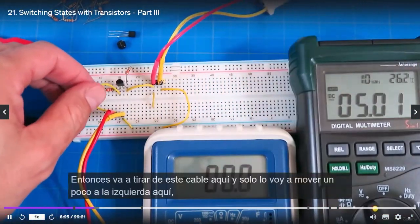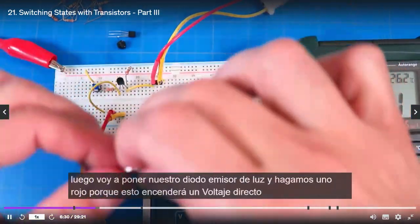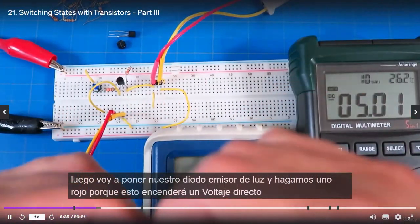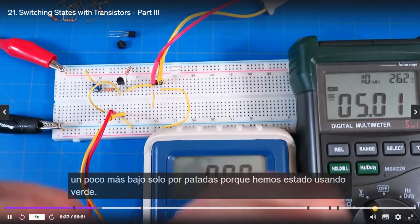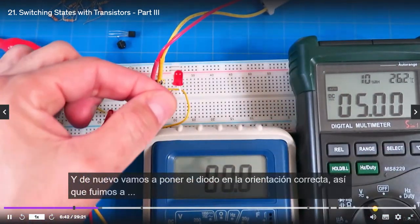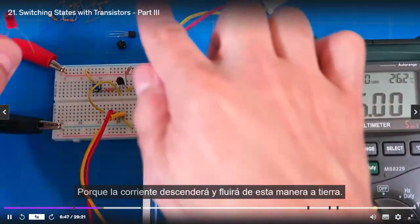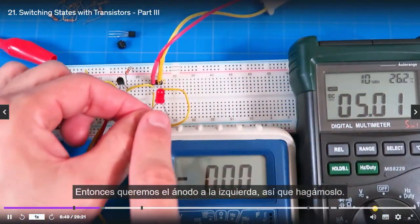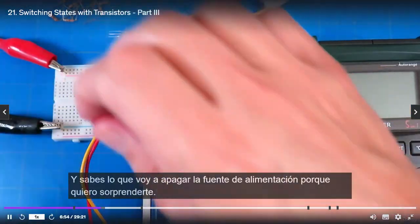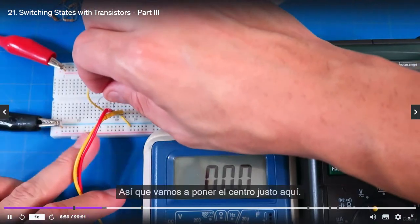So I'm just going to pull this wire here, and I'm just going to move it a little bit to the left here. Then I'm going to put in our light emitting diode. You know what? Let's do a red one, because this will turn on at a little bit lower forward voltage, just for kicks because we've been using green. And again, we're going to put the diode in the correct orientation. So we want the anode on the left because current's going to come down and flow this way to ground. I'm going to turn the power supply off because I want to surprise you. So we're going to put this in right here.